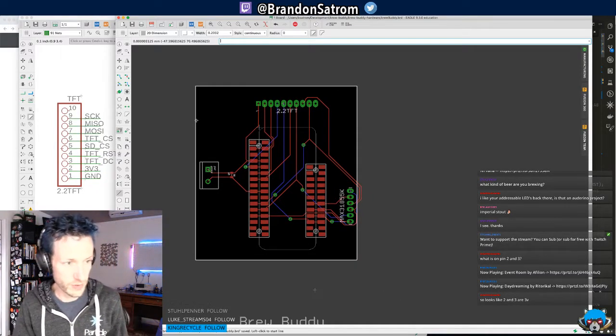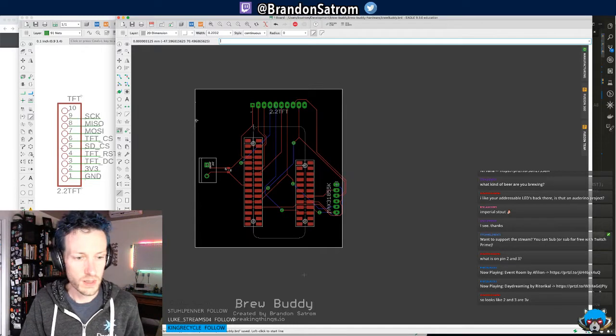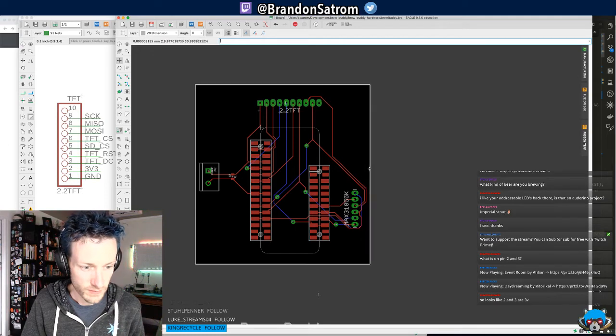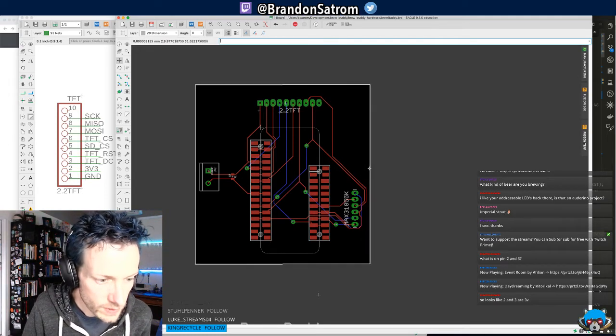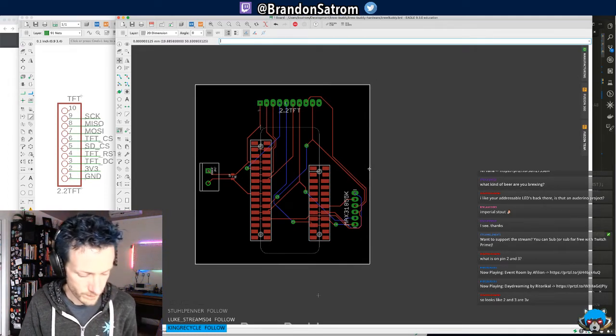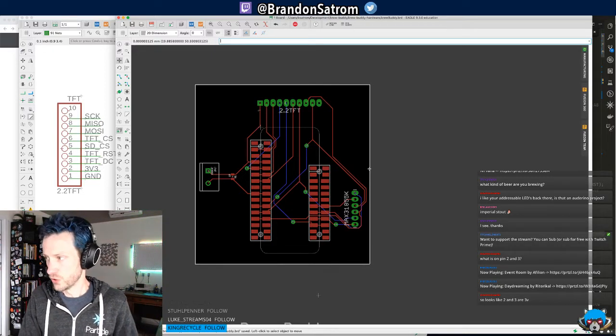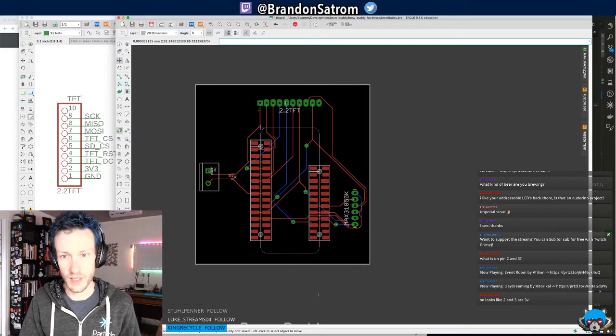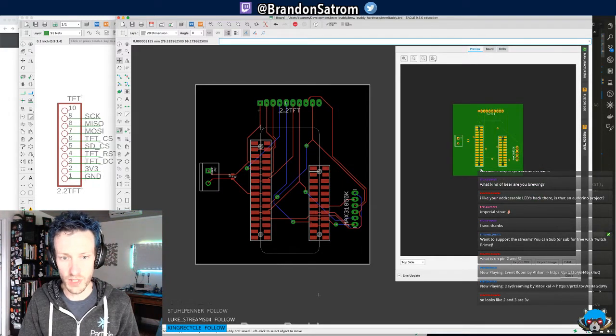So that's that. And you'll notice when I actually create a square, oh, hold on, I gotta move. Some of my wires are outside of the board. So I now have a light gray outside of the board and a black inside, which means that there is actually an outline for the board now.